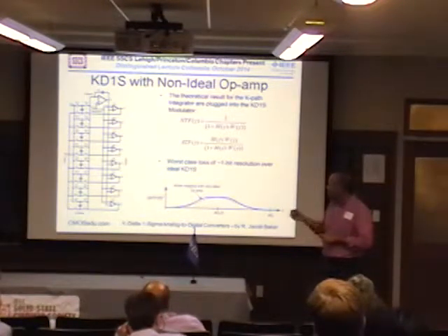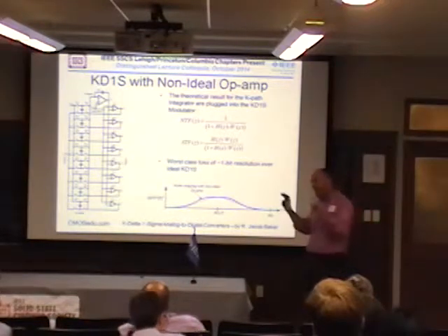Okay. Several things. I did the proof of concept with the switch capacitors. I think it would probably be better for power and for speed if you didn't use switch capacitors and used just RCs, because they would be super tiny. You would need non-overlapping clocks for all those. When you put all those things together, I think it would be really easy to test out, but I'm kind of an academic.